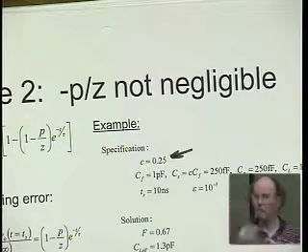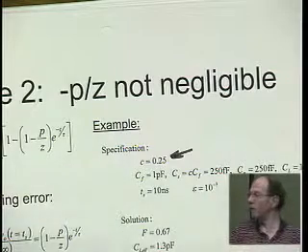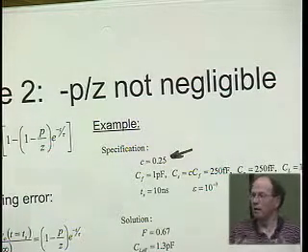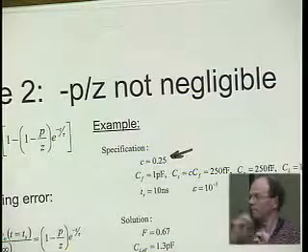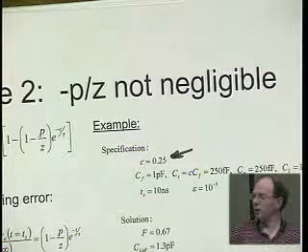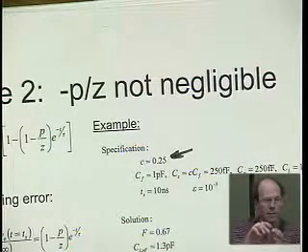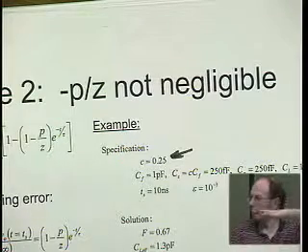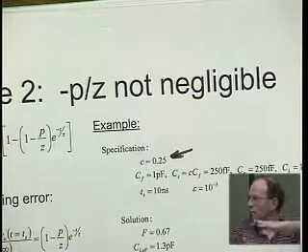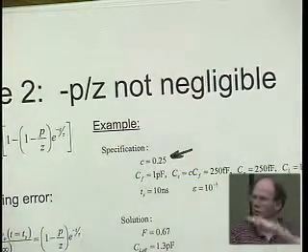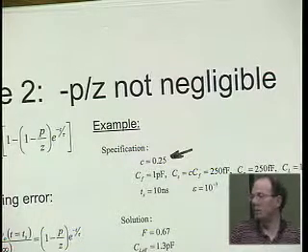Every switch capacitor stage has some gain, at least in the passband, so the signal gets bigger and bigger, and after a while it just gets too big. Moreover, if we have some peaking or ringing, we really need to attenuate the signal so that at the intermediate nodes it doesn't exceed bounds.